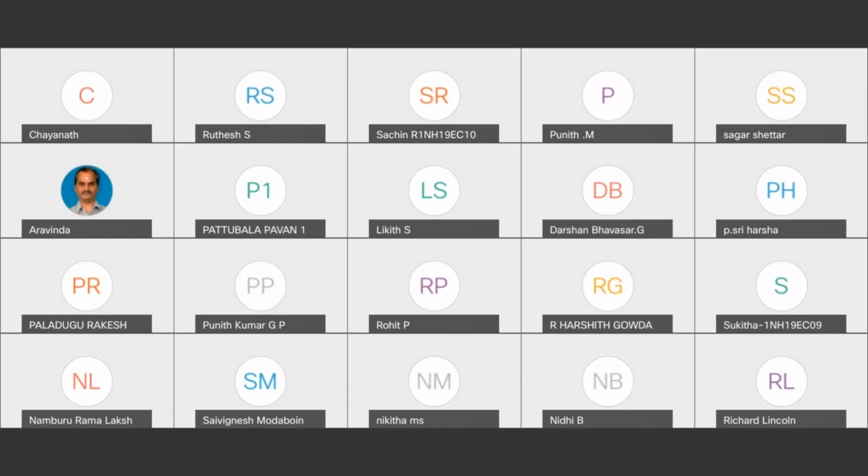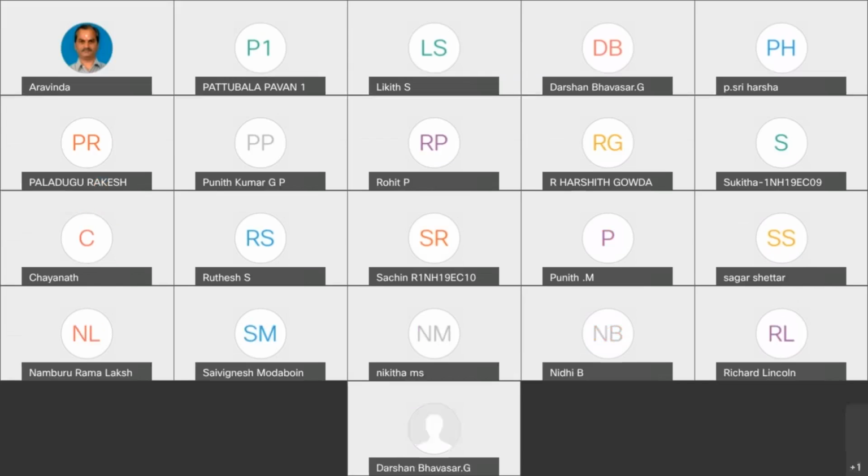But in the next semester, you are going to work with ASIC Design. In ASIC Design, you have to take care about the area or the size there, because in ASIC the size matters. Because in ASIC Design, you are going to design a specific chip. There you should decide what was the total area of the chip and what was the size of each and every element inside the chip, because it is going to cost you a lot. If larger the chip, it will cost you more. So there we really work out on the size of the chip, and that is where you are going to involve yourself in making a layout for the circuit diagram.